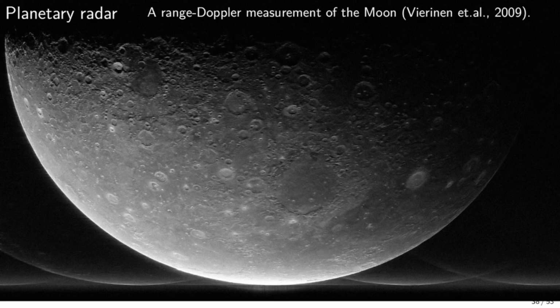The image shown here is a measurement of the Range-Doppler spectrum of the Moon. The brightness denotes the amount of scattered power as a function of range and Doppler shift. In this image, the horizontal axis denotes Doppler shift and the vertical axis denotes range. Due to the range and Doppler variation of different points on the Moon, a pulse-to-pulse Range-Doppler spectrum measurement can be used to map radar scatter power originating from different regions on the Moon.